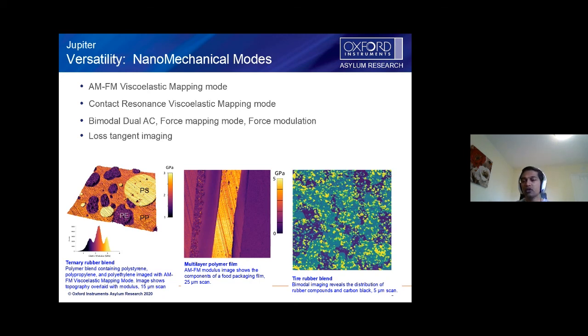Good question. So for doing Kelvin probe microscopy measurement, you want to make sure that the probe has a high Q and a low K. So what I mean by that is the probe needs to have a high quality factor and a low spring constant. The lower the spring constant, the more sensitive your measurement is going to be. So you can use a probe called Asylum electrical probe